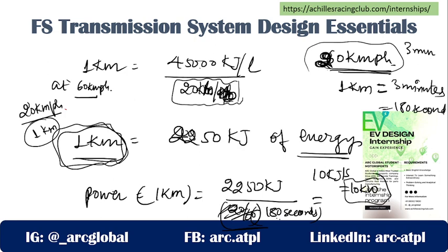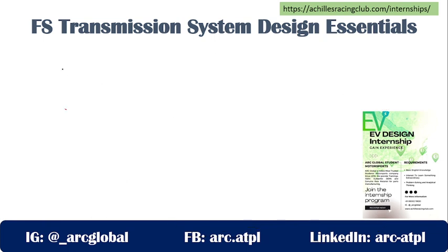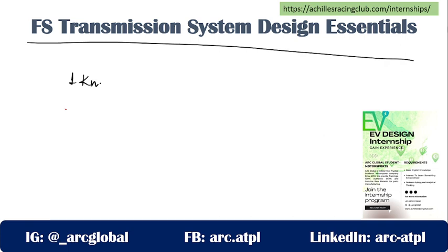It means to move 1 kilometer, how much power is my vehicle consuming? 10 kilowatt. Is it possible? No. What you will find out generally in your vehicles, to move 1 kilometer, you require 100 watt of power. In the case of Alto or Eon, some vehicles in that particular category, you will be having 80 watt to 120 watt.